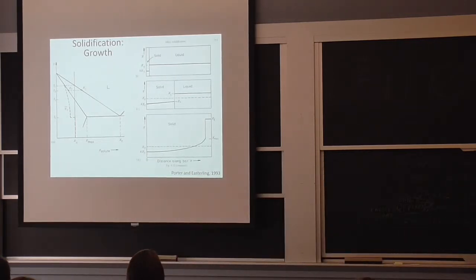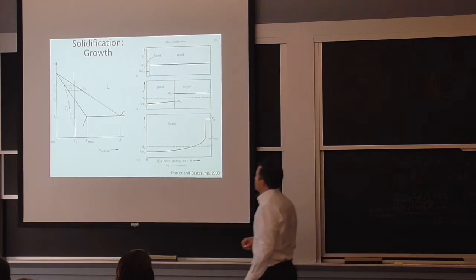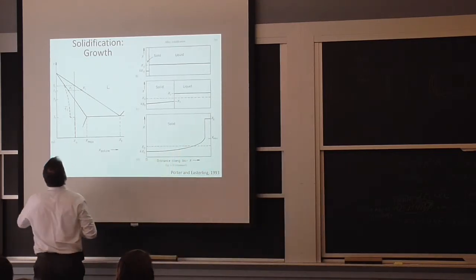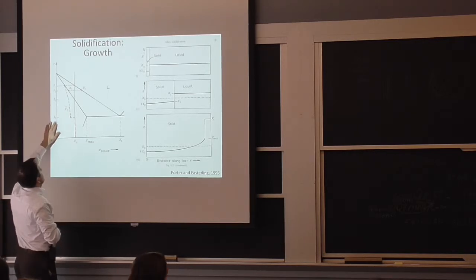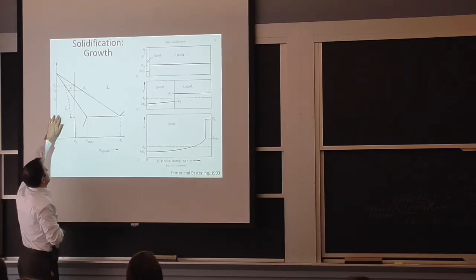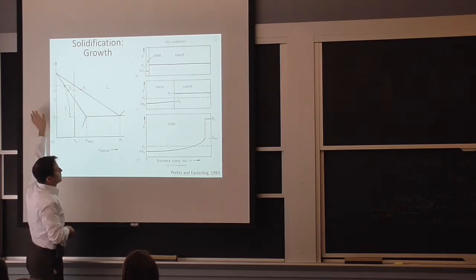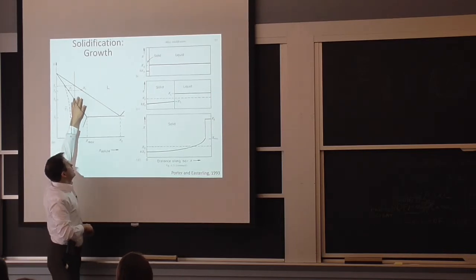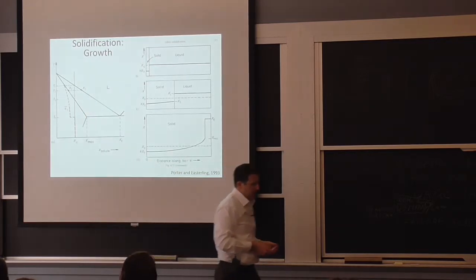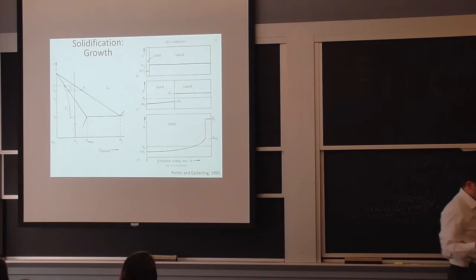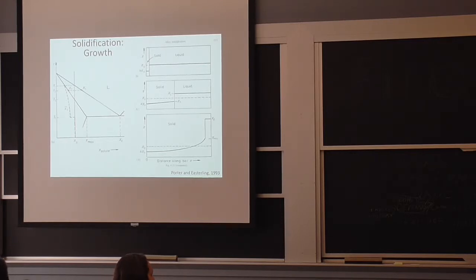So knowing that, we know that at a certain temperature, and you don't need to understand all this, but if you want to know a little bit more, you start by forming a solid that has a concentration closer to the pure alloy, and as you keep going down and going down, you have more solute elements. Essentially, you're forming a crystal, and it doesn't really want to have all these alloying elements, so they keep getting pushed ahead of the solidification front, and we call that segregation.